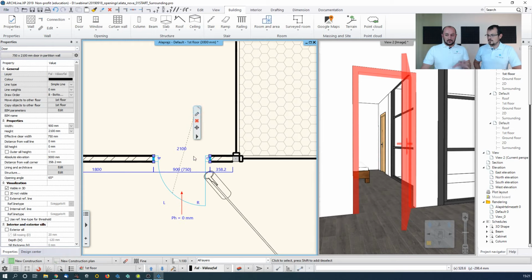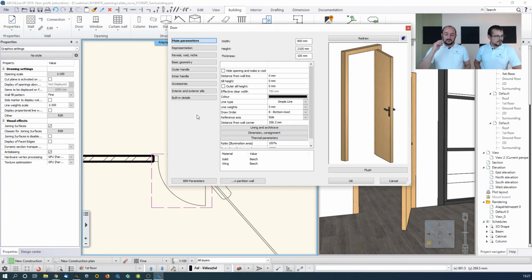You just select the door and you go and edit it with the little pencil. That's a modify button. With the modify button you will be able to reach the door properties. In the generic properties, you can do all the same customization that you could do with the blue markers, and find the sill height, for example, if this would be a window. And there is the solid, and in this case there is only a solid and a wing. The solid is actually the frame and the wing is this material. So this is what you can change.